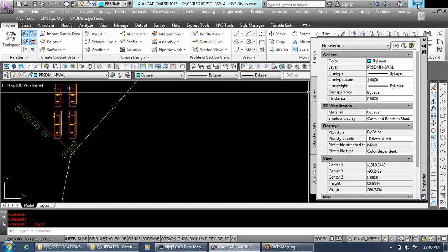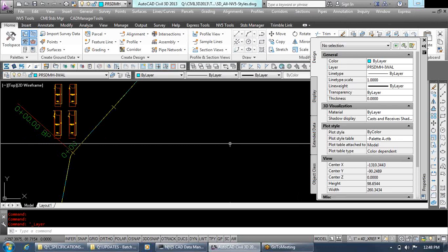The other thing that I noticed is with some of the line text, I'm not sure how it's defined, but we use standard text on it. So if I change the standard text to other than Simplex, it messes up the line type. Right. Yeah, let's keep that in mind. What do you guys think about that? How do you guys use the standard text style? I rarely use it. You rarely use it? I usually use the L10. I usually define my own text based on the viewport scale that I'm going to be using.